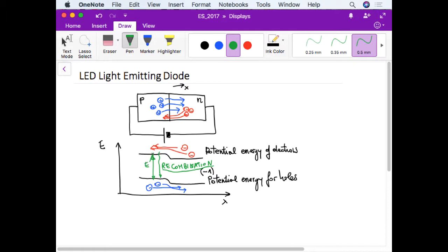because this is the energy of the free electron, and this is the highest energy of electrons connected to the silicon or semiconductor ions. Depending on the type of material, this liberated energy can be transformed in two ways. It can become just heat, because we say it is transformed into a phonon, which is a mechanical vibration of the semiconductor, and that is simply heat. Or it can be transformed into a photon, a quantum of light, which is emitted.